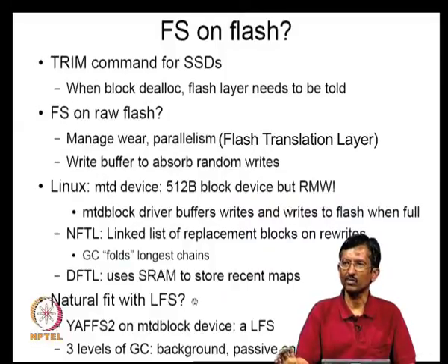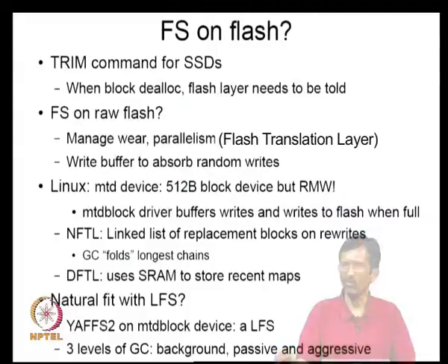If your array size is, let us say, 512 kilobytes or 1 megabyte, then you can buffer all the writes in memory as a log, and every so often you push out these 1 megabyte, 2 megabyte or 512 kilobyte segments and write them in one shot to the flash in its array size units.